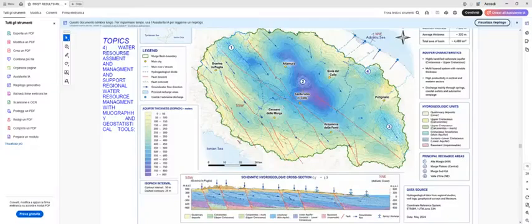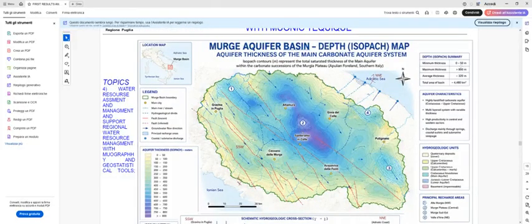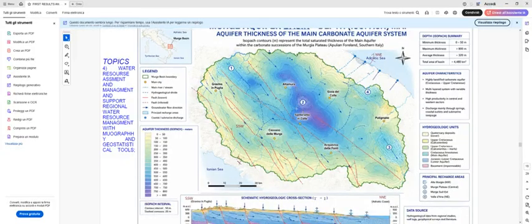The two questions are: first, the thickness of the aquifer, to estimate the total rechargeable volume; the second, how water is moving in the aquifer. The minimum thickness is around 50 meters. The maximum is around 700 meters. So this is the average thickness of the total basin. You can multiply this value with this value and obtain the maximum water storage, the possibility of maximum aquifer storage. Multiply this by this and multiply by the effective bulk porosity.